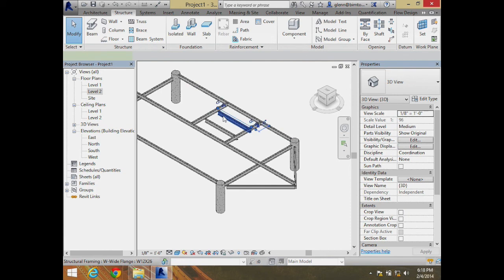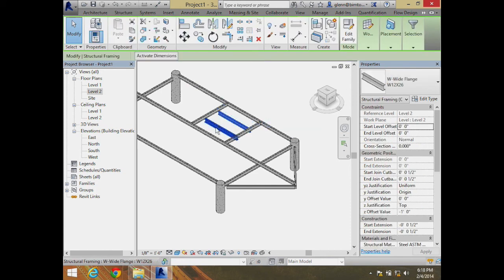And you can frame that down to be just the size of the opening you need it to be. But in general, we tend to have some sort of support really close to the edges, maybe not exactly at the edges, but it's going to be the same rule that applies at the outside edges. There's just going to be some support that's relative to what the floor can cantilever on its own. Putting those in there, you often get interesting little framing systems that go around things like that.